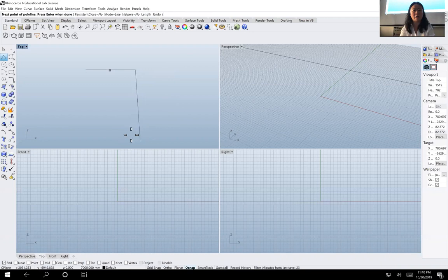Now it's asking you which direction. I type in 7,000 as 7 meters. Now I need to go only vertically, so I press the same key. What did I press before? Shift, yeah. So it's locked to horizontal and vertical. And now you click. So basically 5,000 by 7,000.